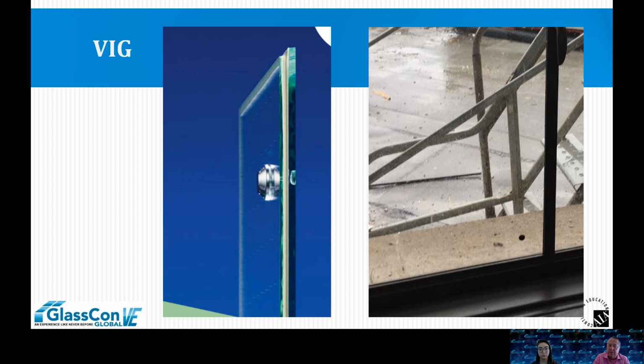The pump out tube has a protection cap that goes over it. And that typically is about a 1/2 inch round or something like that. It varies on manufacturer. That's more visible. And in some cases, if you're doing a really small, true divided light 9/9, you've got a bunch of little caps, it becomes an aesthetic issue.